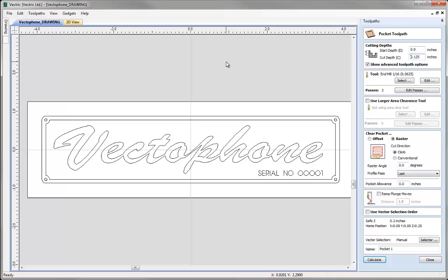If we don't, we could type in Z equals, and that will then display the current depth, or we could also type in just Z on there, and what that will do is that will replace the Z value with whatever the Z depth is in the material setup. So this is future-proofing this toolpath, so that in case we do decide to do a slightly thicker or slightly smaller depth in the future, this toolpath is always going to alter that dependent on what the actual material setup Z depth actually is. So we'll leave that as Z, and we're going to choose our tool.